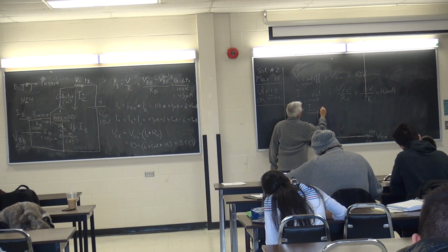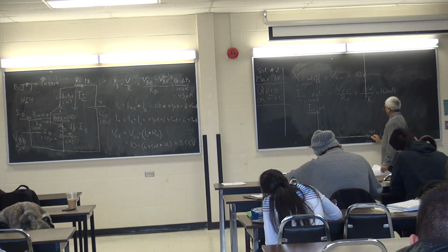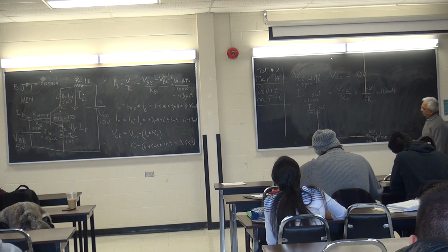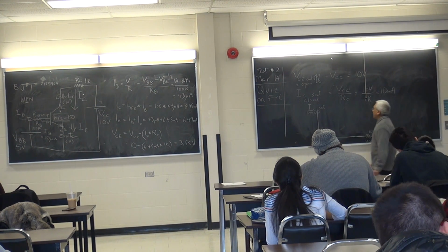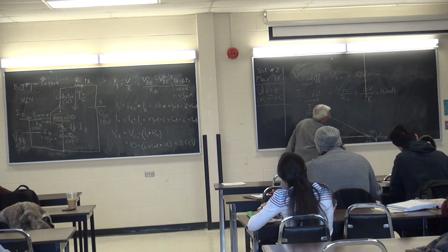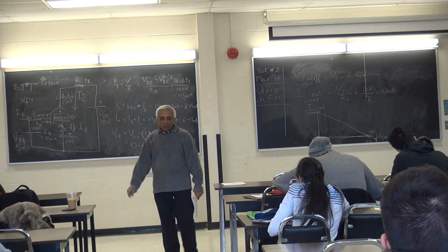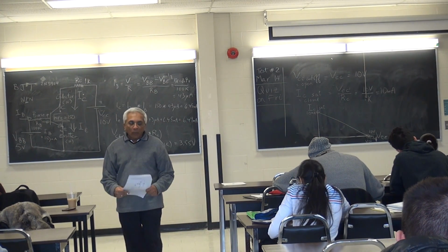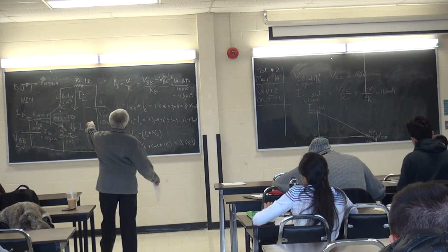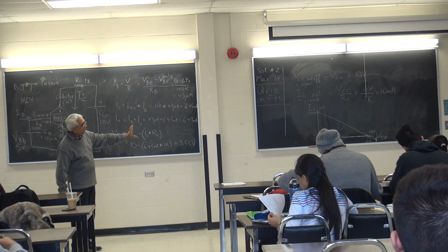Write down SAT here, write down cutoff here. Okay, and then draw a straight line like this. And then we're going to show on that straight line where this circuit is operating at. So basically what I've shown there are the two extreme points.